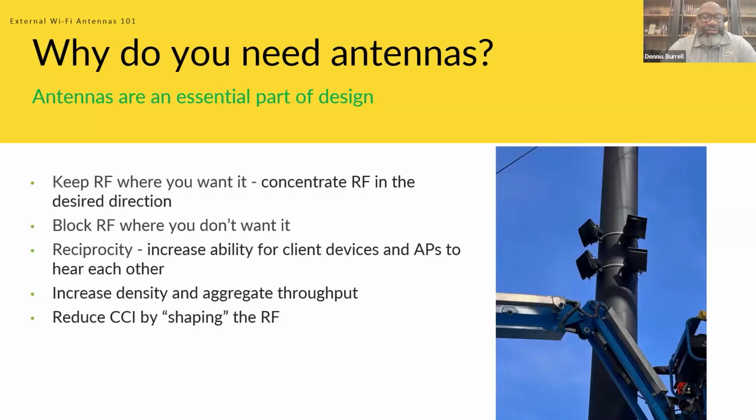So why do we need these? Why do we need antennas in general, but more specifically external antennas? The antennas are the central part of the design. They keep RF where you want it and concentrate it in the desired direction. As Troy mentioned a little earlier, good, better, best. I would look at it from that perspective as concentrating the Wi-Fi in that direction. You can block Wi-Fi where you don't want it.